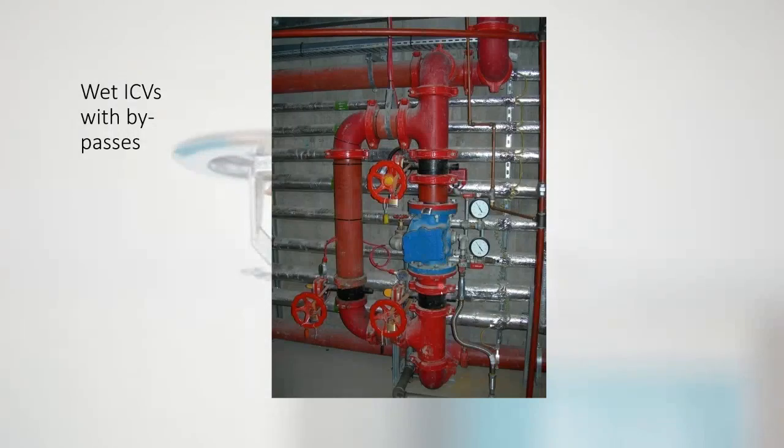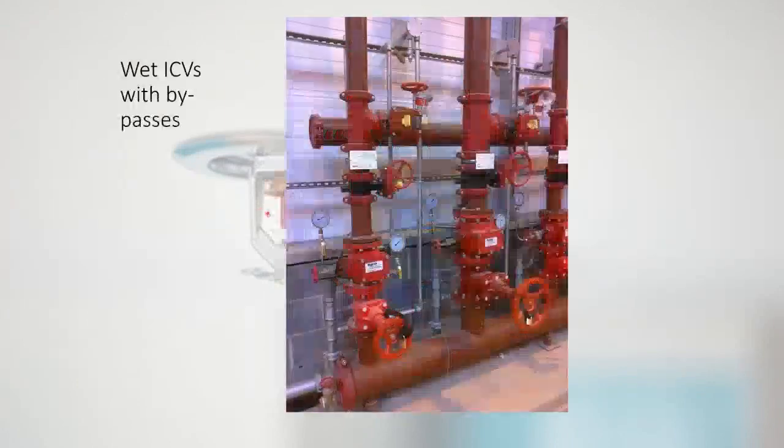We can then drain this small part of the system, take off that cover plate, do whatever maintenance needs done, and put it all back together. It makes it quicker, we don't need to drain the system, and it's easy to put back online. So when we're finished and we're happy with it, we will open that valve, and then shut that valve. And during the maintenance, we've always got a sprinkler system. Always. Now when you've got multiple sets of valves, what you can have is a combined bypass valve running along the back. You may find that in big warehouses.